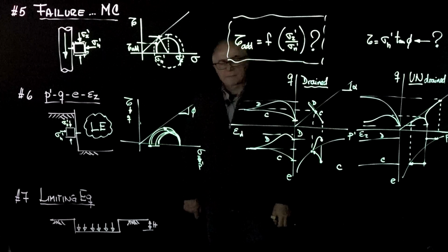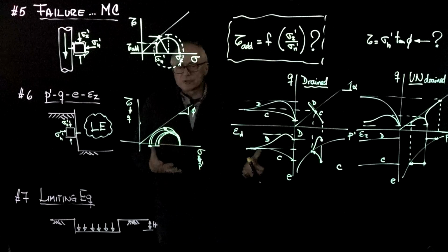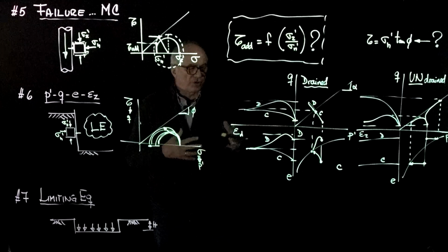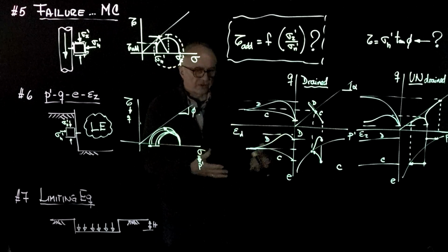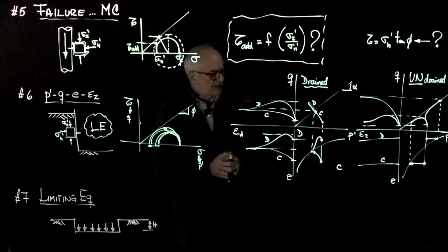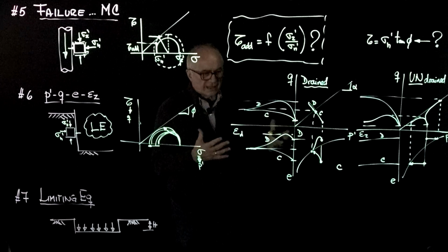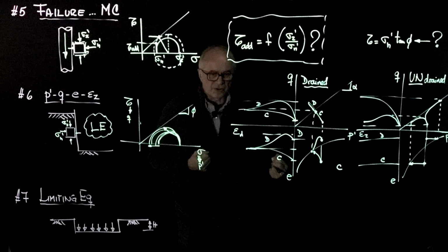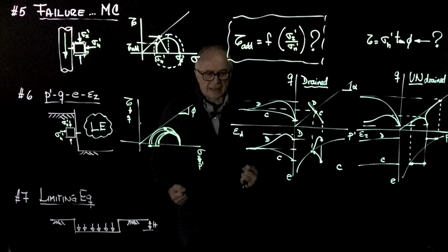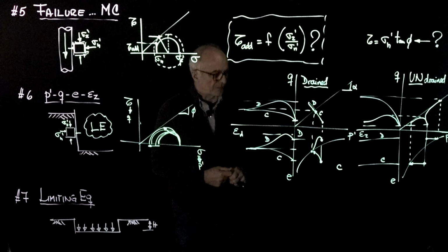So folks, you will have to use a robust constitutive model to capture all these paths, to capture the natural behavior of soils, which is not necessarily what you get with the simplest constitutive models. But you can grasp the trends by understanding the interplay between effective stress, volume change, and, in the absence of volume change, effective stress and pore pressure generation.